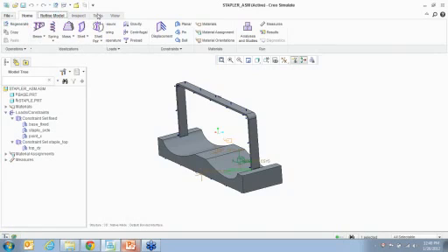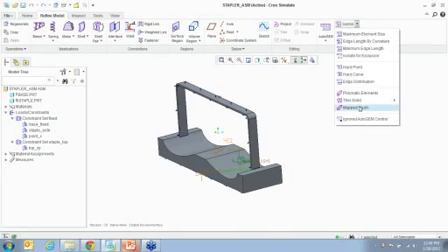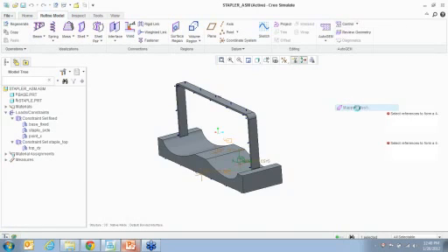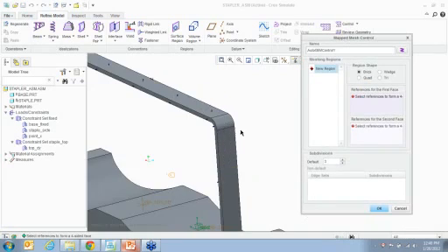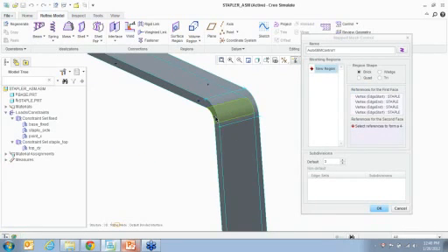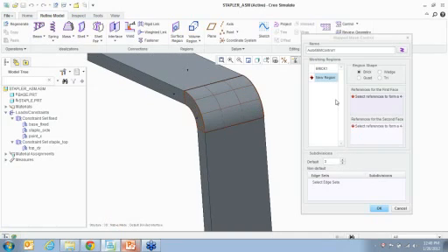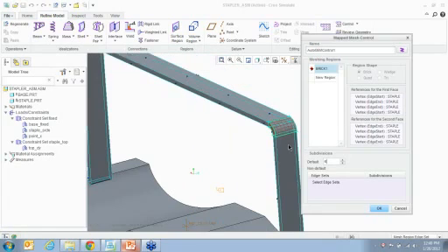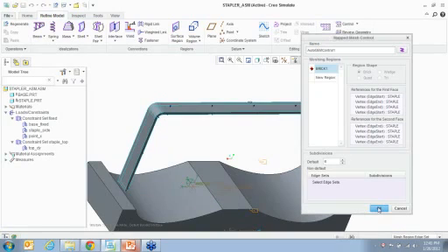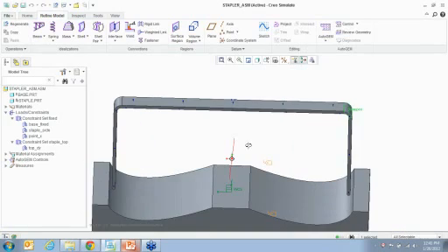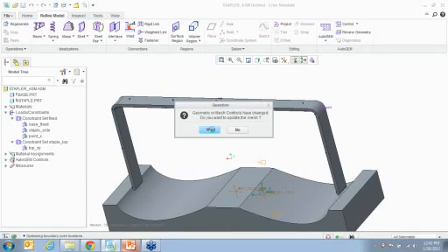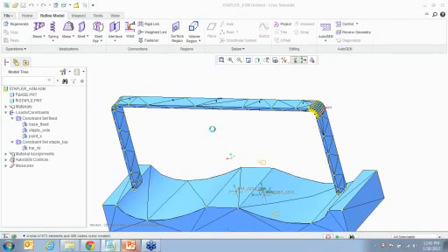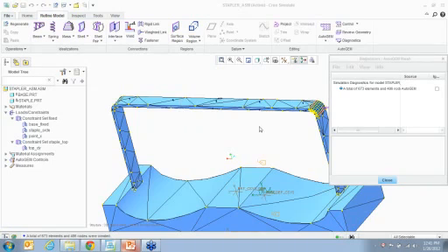Also, in terms of meshing, if you go to control, you look at map mesh, we can go ahead, pick a couple of those surfaces, and notice how you have an option to increase or decrease the elements over there. I'm going to not do it on this side so you can see the difference. We can go ahead and mesh it real quick.